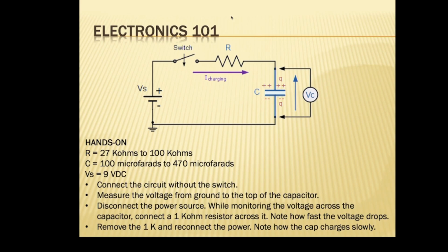So this is 100 microfarads, 450 volts. Can I use it with 9 volts? Yeah, you can use it with 9 volts. It's way under its rating, so it's fine. But you wouldn't want to put 500 volts on it. 500 volts would probably let the smoke out, meaning it would go poof. As long as we're underpowering it, yeah.